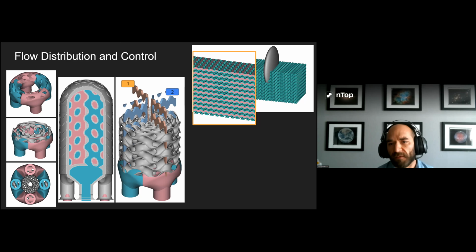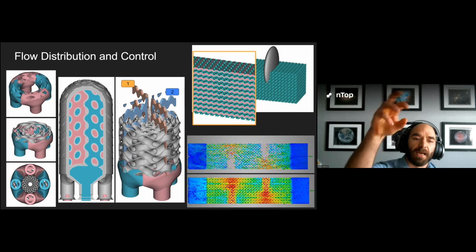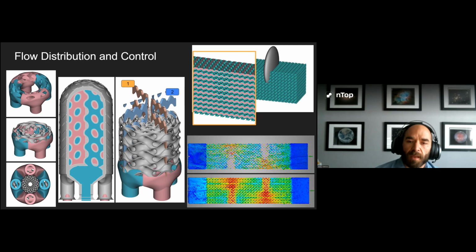If you follow my mouse on the right, we're moving through this red flow area. We're going to transition slowly to a choked region. We're not completely cutting it off. We're going to transition back to our normal flow area. What this does is it encourages most of the flow to move in and around the structure. So we're increasing the time that we're in the heat exchanger, but we're not impacting the pressure drop as significantly.